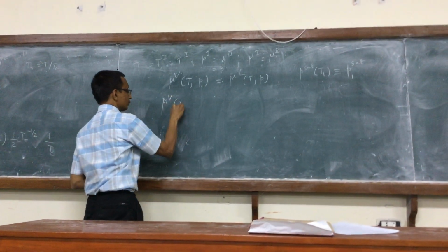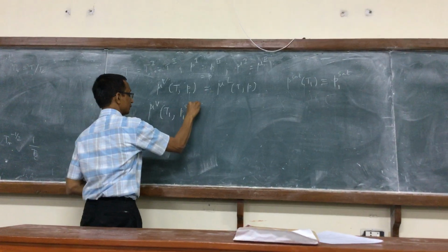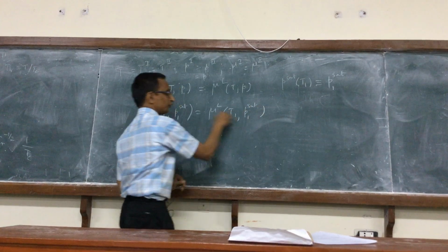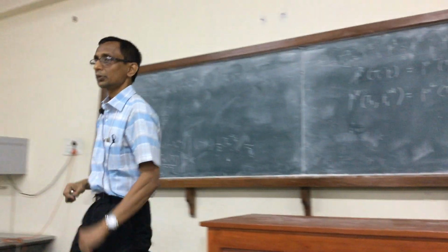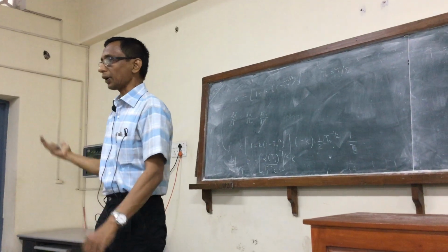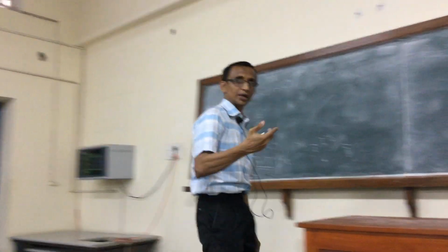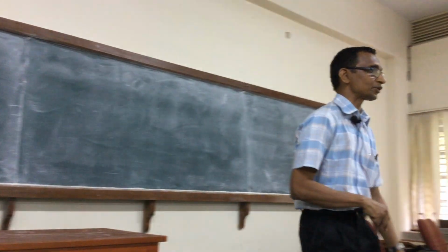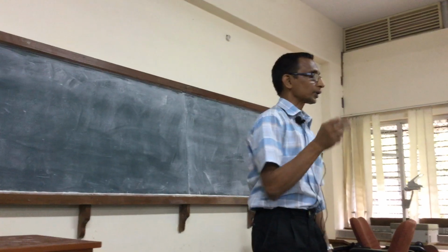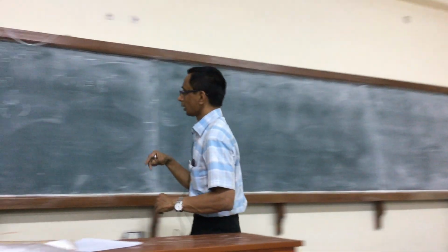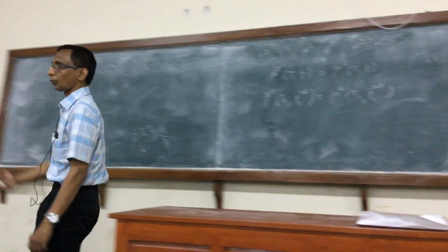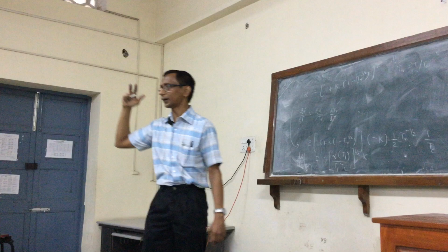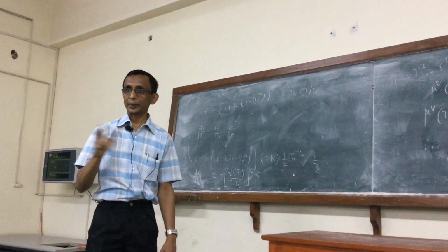So I'll write this as P1 sat. So if you give T1 in this equation, then I solve for P1 sat. It can be also the other way. I could be given the pressure and then we calculate what is called a boiling temperature. Usually not called the saturation temperature, but rather the boiling temperature. It can also be there. We will take up this problem, which is what is handled mostly, but the reverse is also easily handled. These equations are the same. Only what variable is specified will differ.